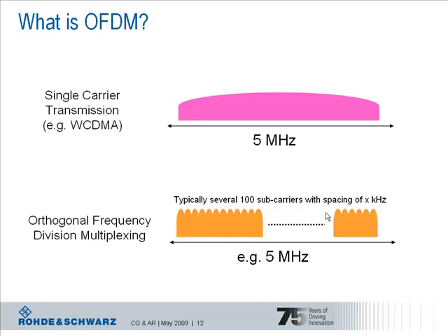The figure shows an example for the 5 MHz bandwidth, and you see the subcarriers. But of course, you can easily scale the OFDM principle also to higher bandwidths, like in LTE, where you have up to 20 MHz bandwidth. Compare the OFDM transmission with a single carrier transmission, for example for wideband CDMA. Since the multiple subcarriers in OFDM are transmitting in parallel, each one can transmit with a lower symbol rate, thus improving robustness of the technology for mobile propagation conditions.